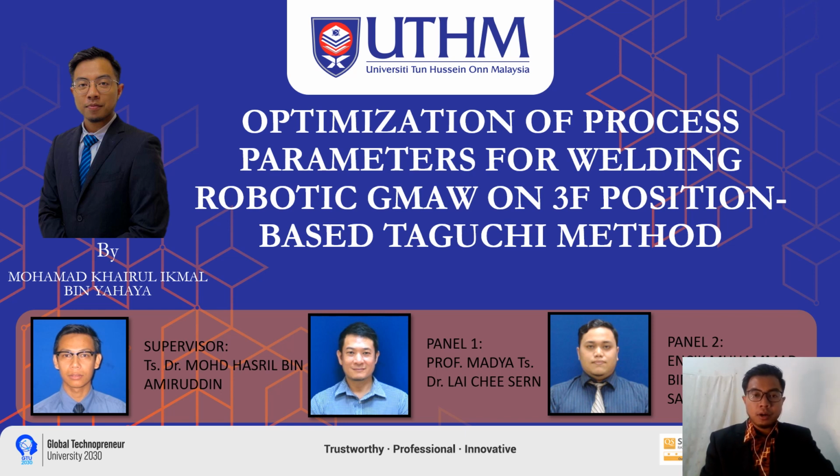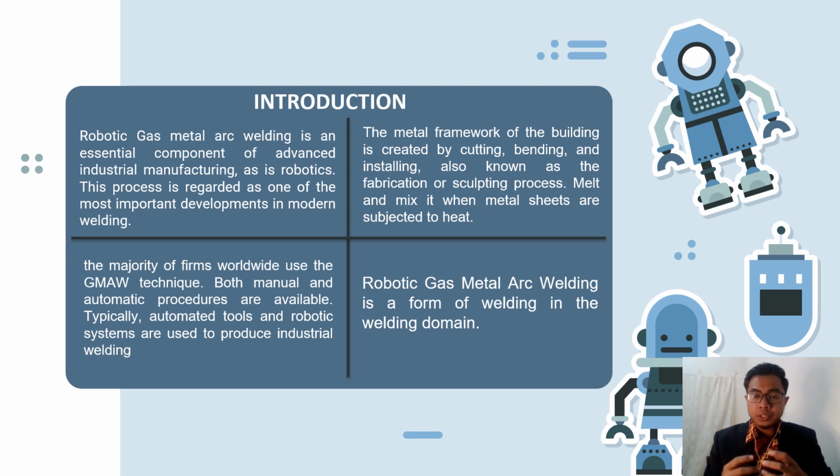My research is optimization of process parameter for welding robotic GMAW on 3F position based on the Taguchi method. Okay, next, we are going to the introduction about this research. Firstly, what is optimization? Basically, optimization is the action of making something the best and most effective. In this case, it is the parameter for welding robotic GMAW on the 3F position.